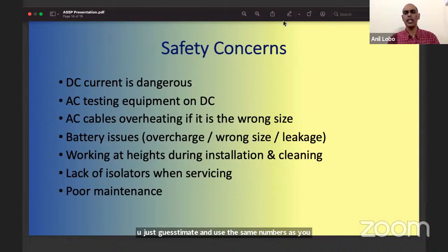AC, you are in deep trouble, because the moment you fire up the system, you're going to damage first the insulation. When the insulation cracks, the cables are going to touch each other, they're going to short out. Once it shorts out, it'll overheat and can cause a catastrophic fire. If it is next to a battery, the battery itself can explode.